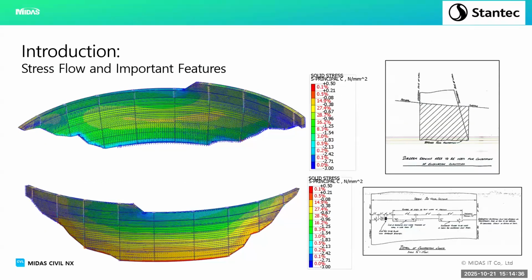So now we look at this, which is just under hydrostatic load, so nothing else. And we go back to it now. And these are the principal compressive stresses. I know generally when people look at it, they look at the horizontal or tangential, otherwise referred to as arch stresses. But I do primarily look at your principal compressive and principal tension stresses. Now, you can see, as I said previously, the upper two thirds is pretty much a hoop stress there, very horizontal.